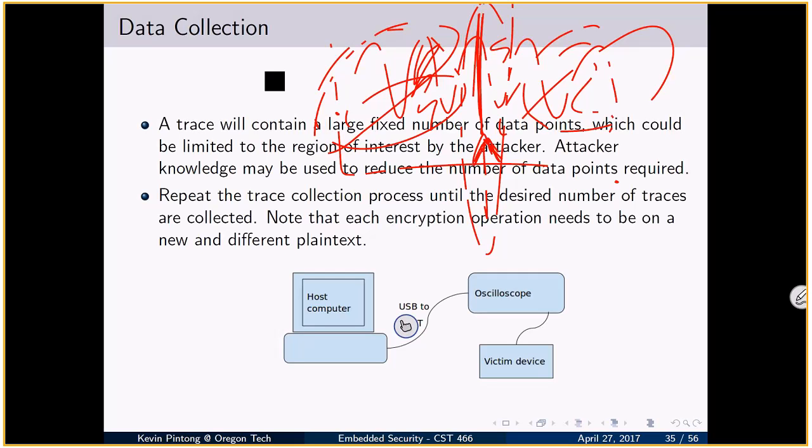Once you produce those profiles of, let's say, 256 values, once there's a correlation at that point, you can probably determine the correct key using that Pearson correlation coefficient. That's how we're doing it. And the Pearson correlation coefficient normalizes the data set, so it gives you a value relative to the overall signal.